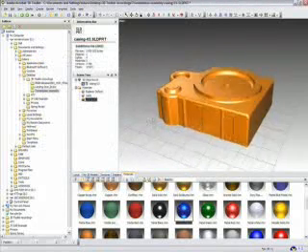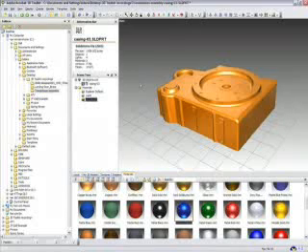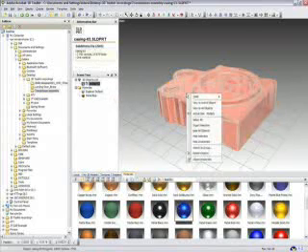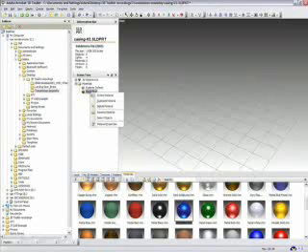In order to add the material to the available list, you need to perform a series of operations to isolate the material in the 3D scene. First, right-click on the Materials folder and remove all of the unused materials. Then, select the object and delete it from the scene. This leaves only the Explorer default material and the metal blue material, which I changed to orange. Now I can right-click the material and rename it from metal blue to metal orange.